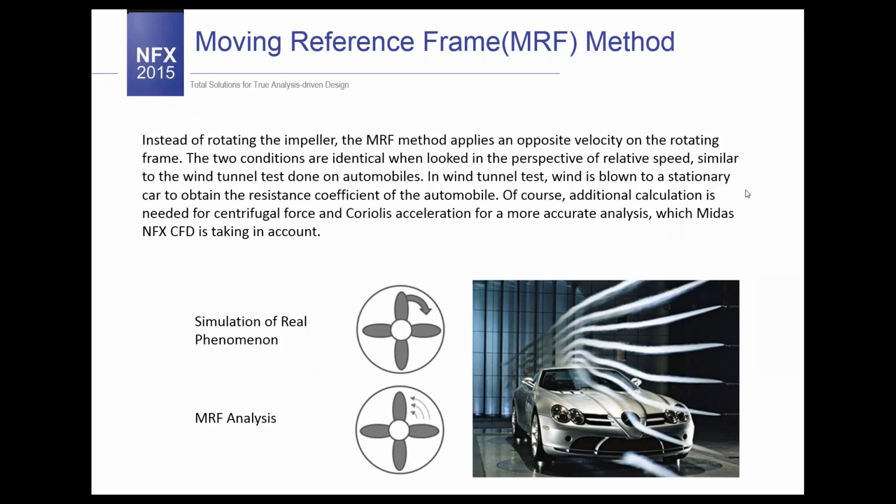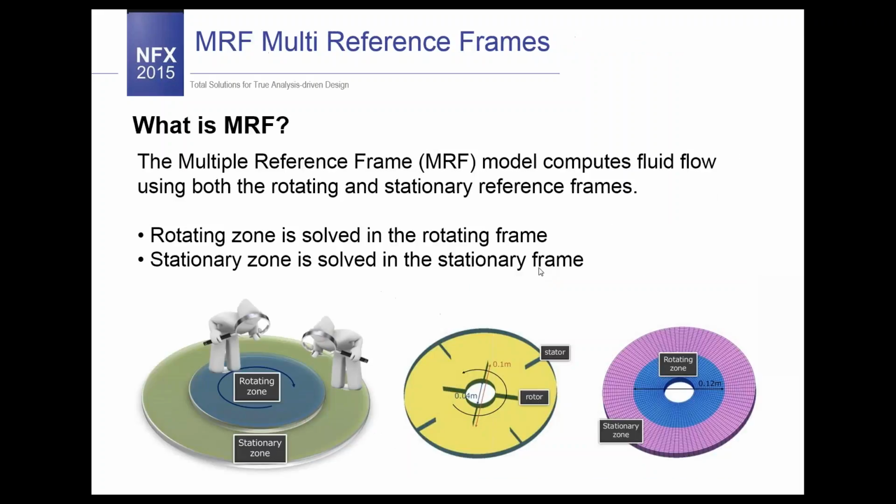Okay, I have one question from someone who is asking, in the previous example, how I can get the torque from the analysis. So you can get the torque by analyzing the pressure on the blades. Once you do the analysis, you have an option to investigate the pressure which is created on the blade, and this basically gives you the torque after you calculate it.